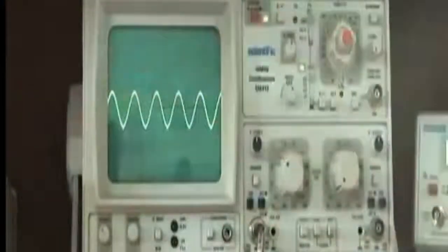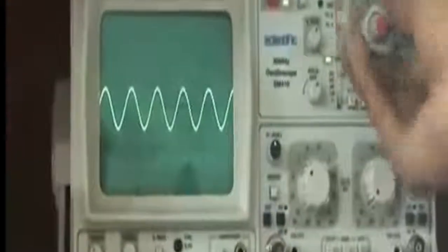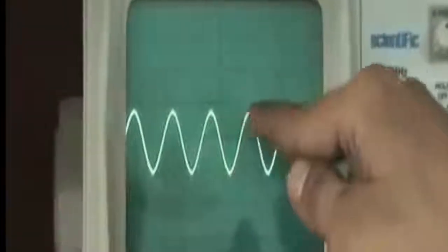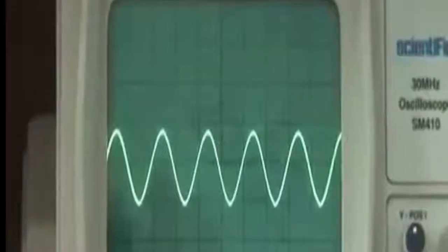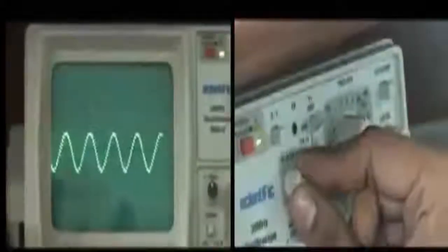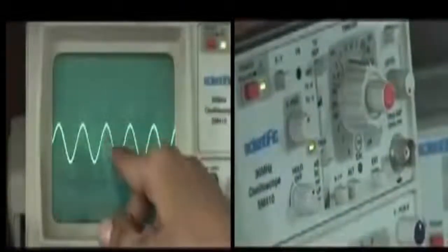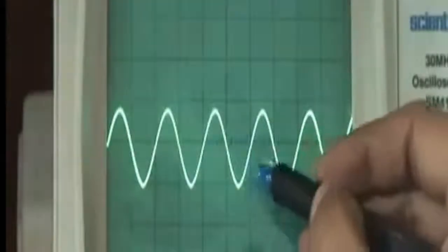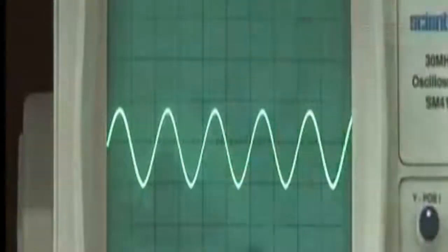And what about the x-axis? The x-axis can be changed using this. What lies in the x-axis? In the x-axis, there is the time. Time of what? Time of how many blocks one cycle of the signal takes to complete its rotation. Using this X position I can move in the X direction. So I am setting it in a proper place where I can take a reference point here, and say that this is going to be 1. From here it is going this way, and till here it completes one cycle. So from here I can easily count the number of blocks.